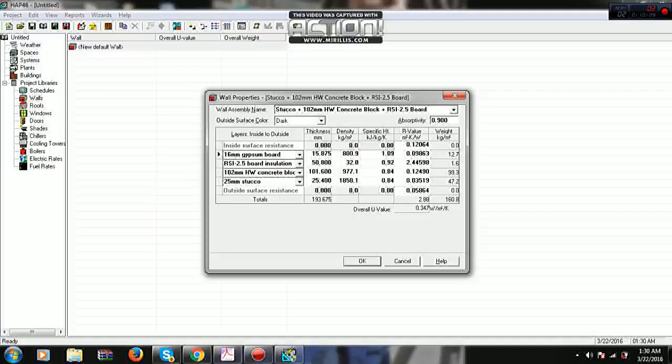How can I make it? Now, if you see here, insulation makes a very big difference to increase or decrease the U value. For example, if I increase the insulation thickness from 50 to 60, you can check the U value, it dropped. But I want 0.437, so I will drop the thickness to 25. And I would like to say this is a trial and error method.